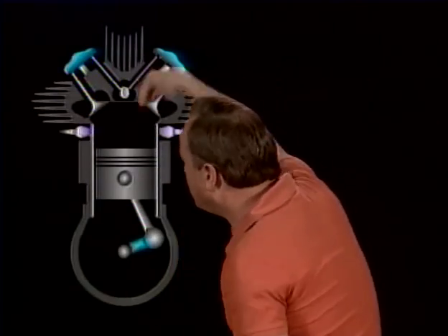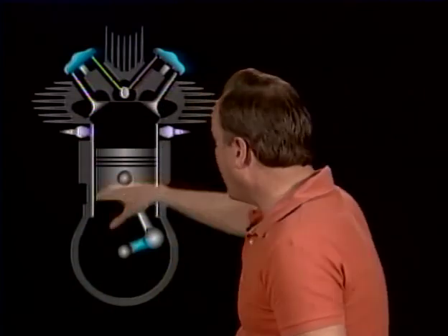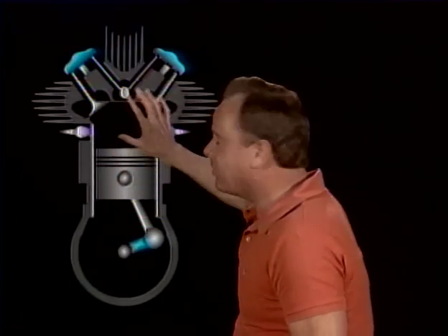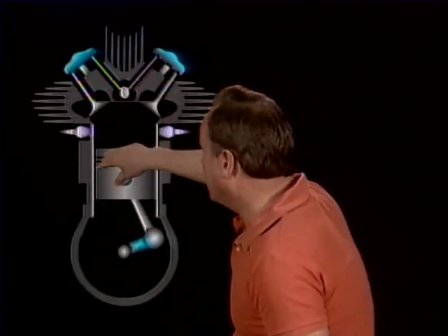All right, once again, let's you and I go back to a differential pressure tester, and you're doing a compression check. Let's assume the propeller moves in the direction of rotation when you put pressure in the cylinder. What does that mean? That means the piston was positioned past top dead center. You should have the piston at top dead center.